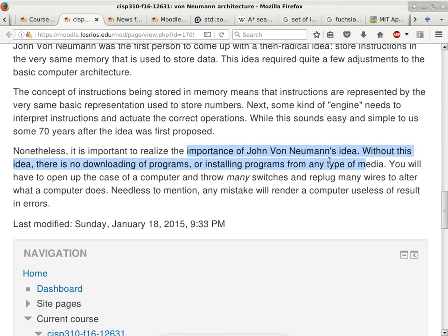So the way it works is, you can use UV, ultraviolet light, to erase an existing program, and then reprogram it, and then if you don't like the program, you can erase and program again. But the downside is it takes 15 minutes of exposure to high intensity UV to erase the program. So it still takes time to do it, but it is a lot better compared to just PROM, because now you can reuse chips. And when I started to get into industry, some in 1990, they were using EEPROMs a lot on single board computers.